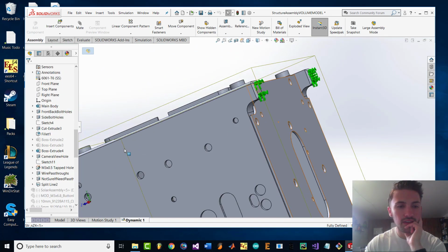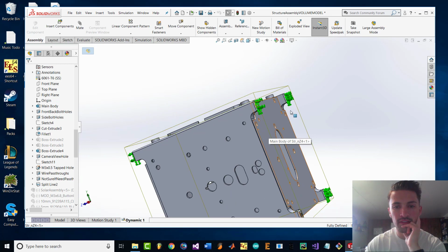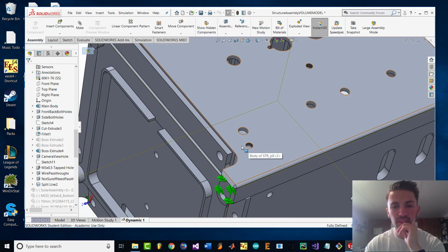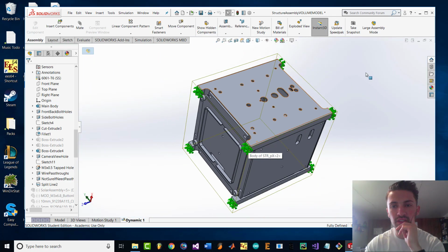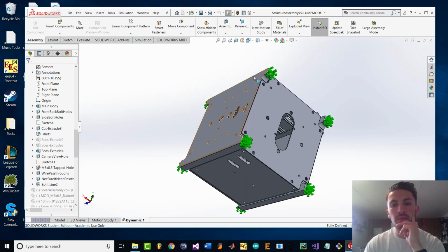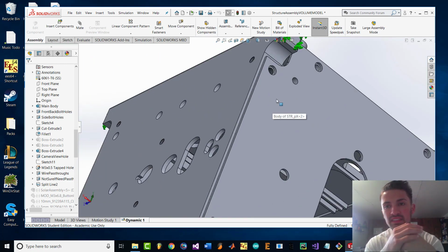One thing you will need to pay attention to, I don't know off the top of my head which one of these holes I could do it to show this error. But sometimes as you're creating these split sketches or split lines, because some of these parts are mated, like the two holes are concentric with each other for the mating process, when you create this sketch, you'll create a conflict with the constraint.